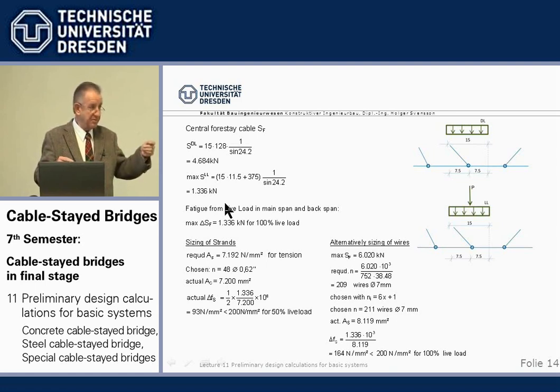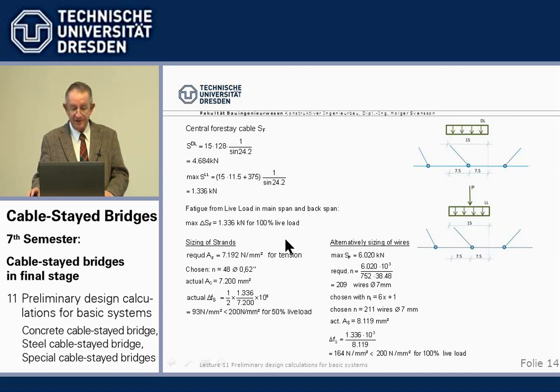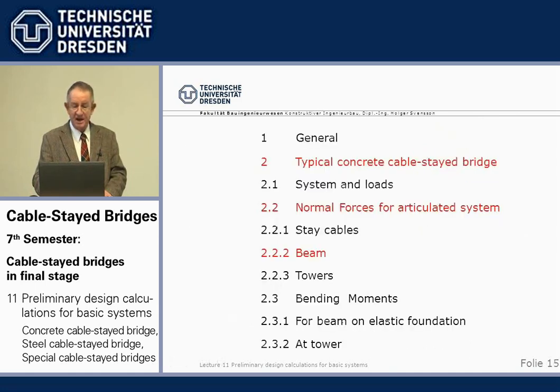The backstay cables are the only ones in this preliminary calculation which get compression. So there we have just a size for the maximum tension force. That is a very straightforward, rather simple operation. So in this way we can size all the stay cables. Simple. It is simple. Just go through the figures.